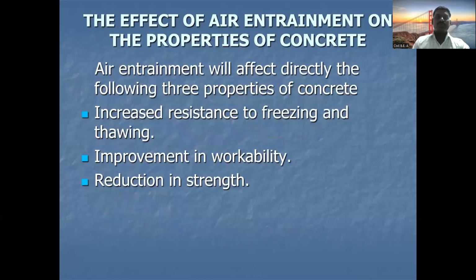So, the effect of air entraining on the properties of the concrete. There are various properties of concrete: strength, workability, then durability. Such properties are very important if we add such admixtures into the concrete. If we add air entrainment into the concrete, what effects will there be? If we use air entraining in concrete, air voids are formed, and those air voids increase durability and decrease permeability. Then why use it, and what is its effect?